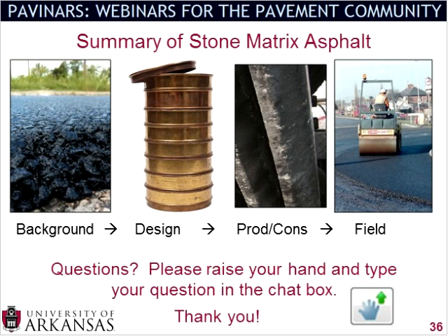Yes, so that's a very good point. What Danny's talking about is if you sand pavement on a regular basis, like during the winter, if you put de-icing down, those type of things, or in general any deleterious material, how would that influence the openness of the pavement? If the SMA has been put down in order to help the drainage, you will want to try and keep the SMA clear. And I didn't read anything, but I know on other open mixtures you can actually use high pressure water to clean out open graded mixtures in order to maintain those voids.